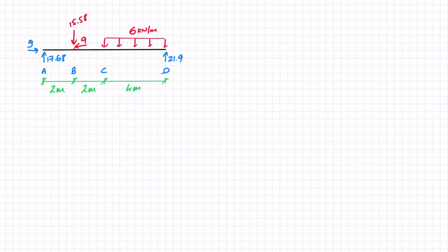Okay, so if I look at the beam first to discover where we're going to cut, I can see that between A and B, I start off with my reaction forces, so I'll probably want to know what they contribute to the internal forces. B gives me an extra load, so definitely want to know what's happening here. And I'll also want to know what happens between C and D when I have my UDL. So 3 cuts. Okay, starting off with the cut A to B.